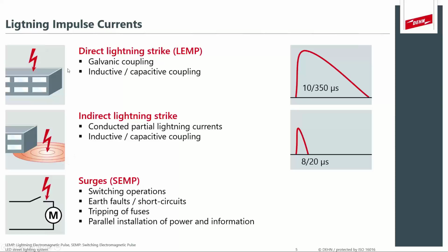It's actually not direct strike. So direct strike carries a massive amount of energy, which means that you will have physical damage to your structure or fire and so on, whereas an induced or indirect strike actually just causes a surge in the electrical system, and that's the common tick and your television is broken and things like that. It's not actually a direct strike, it's more surge.